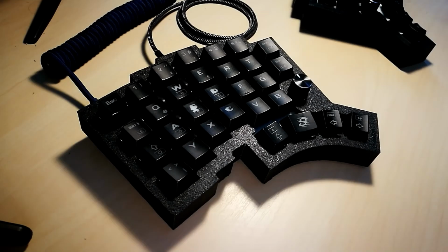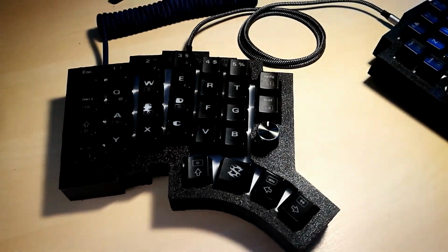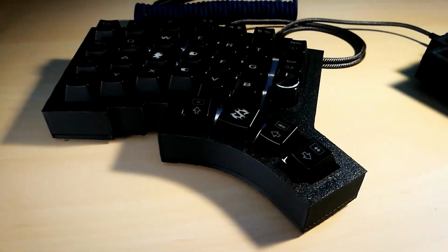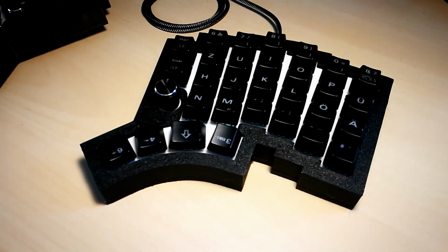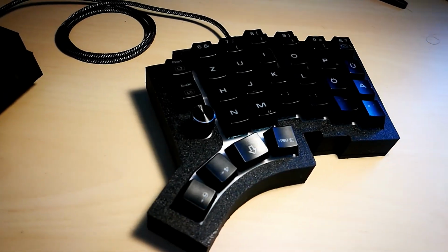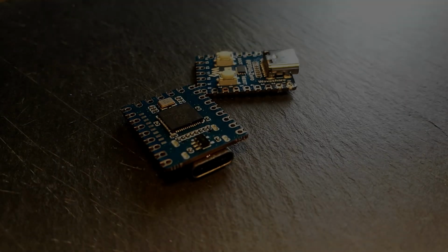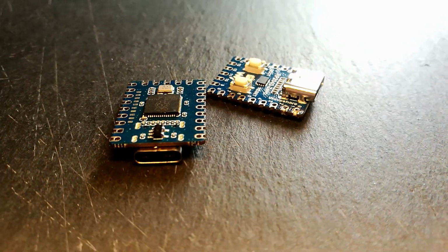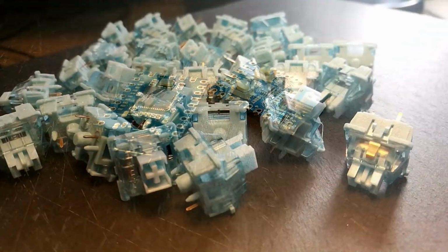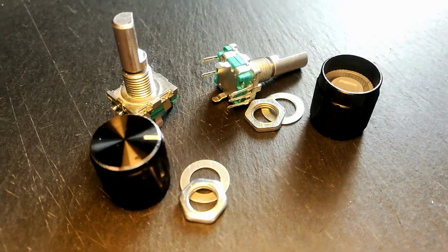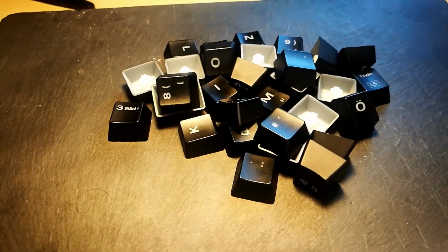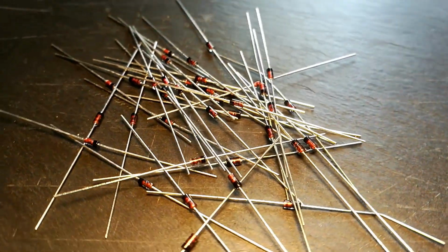Step 2. The equipment. Now that you've decided on what exactly you want, you need some equipment for the build. I will just show you what's needed for this specific keyboard. If you want to build a different one, adapt it to your needs. So what you definitely need is 2 microcontroller. I'm using 2 RP2040s, 60 switches, 2 rotary encoders, 60 keycaps that fit the design, 62 diodes, 1 for each